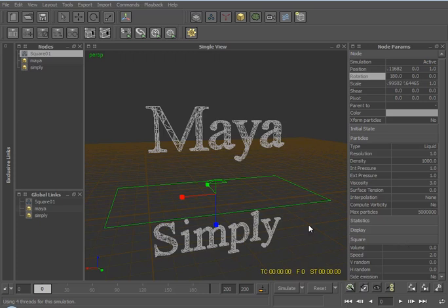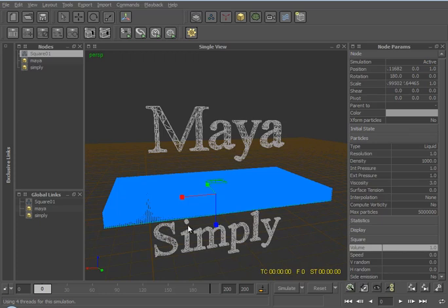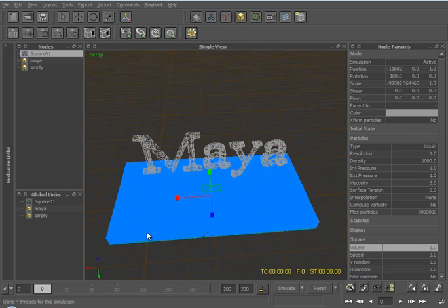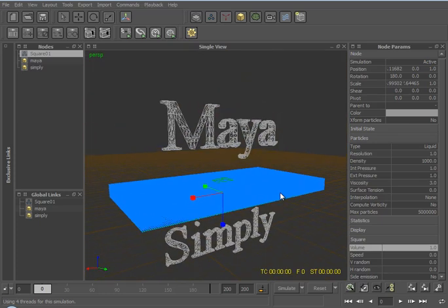And under the square, which this is a square emitter, I'm going to set the volume to, let's just say 1 for now. And as you can see, I've filled the volume with all of these particles. The problem is that the more particles you have in RealFlow, the longer it's going to take to simulate. And at the minute, I have 5 million, which would take us weeks to simulate, probably on our standard sort of system. So I'm going to bump this down to 20,000 particles.